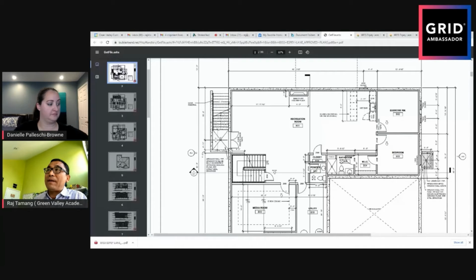So let's say this is a 5 foot opening. I'm not going to have only 5 foot, because I have to put a 2x6 on this side, which is 1.5 inches, and add another 1.5 inches on the other side because you have a 2x6. So instead of 60 inch, I have 63 inch. So make sure when you pour the concrete for the basement wall, the opening you leave should be a minimum of 63. I tell them to leave 64, just to be on the safe side.